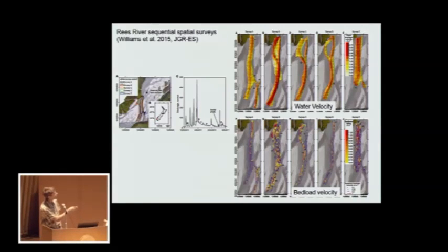So I've got the water velocity in the Anna branch from those 5 surveys, and here's what we're going to focus on, the bedload velocity. I've used the uncertainty model to map where I'm confident that we actually had bedload during those surveys, and those locations are in yellow. So you can see that on the falling limb of the big peak, much of the reach was transporting, had high bed velocity, and I have 95%, actually 90% confidence, that it was moving.